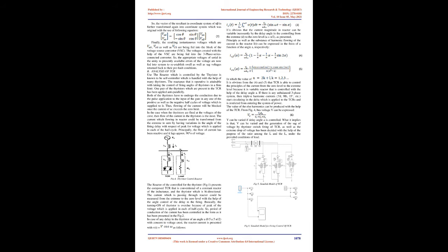3. Controlling the system. A. Control of a dynamic voltage restorer. Using the equation written below, the instantaneous values of the three-phase voltages are transformed into the αβ coordinate system. The resultant vector consists of Vsα and Vsβ. Also, the reference voltages are achieved with the help of the controlling strategy. The error voltages are attained by comparing the voltage components with their corresponding reference voltages, and the resulting difference voltages are injected into the system using the dynamic voltage restorer.